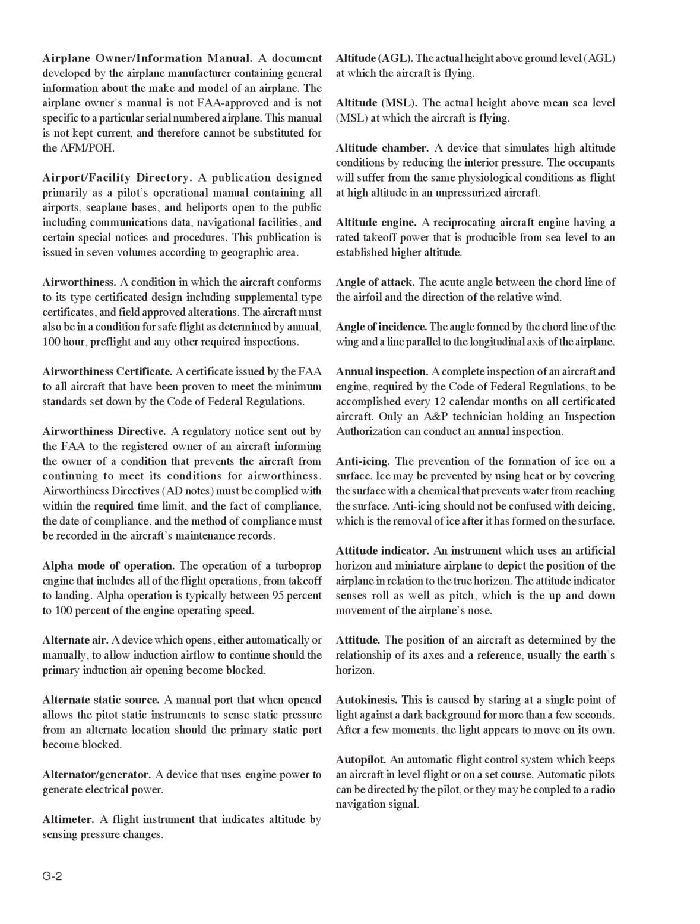Airworthiness Directive. A regulatory notice sent out by the FAA to the registered owner of an aircraft informing the owner of a condition that prevents the aircraft from continuing to meet its conditions for airworthiness. Airworthiness directives, AD notes, must be complied with within the required time limit, and the fact of compliance, the date of compliance, and the method of compliance must be recorded in the aircraft's maintenance records. Altitude, AGL.